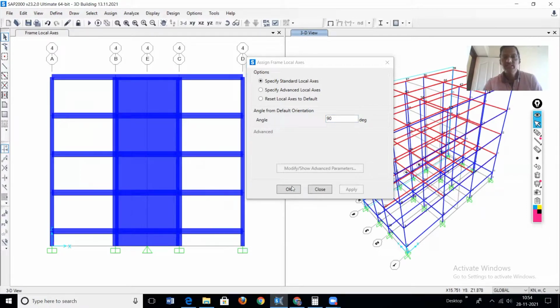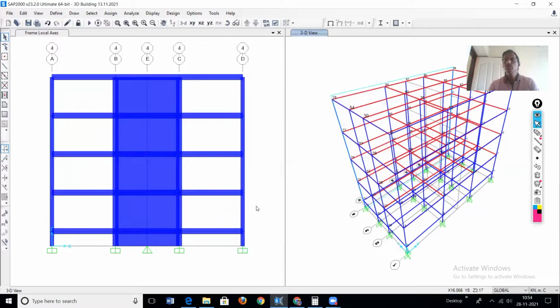Okay, now this is about the definition of the shear wall as a wide column. Okay, and then assign the nonlinearity to this particular wide column, just like a regular RCC column. So in SAP 2000 there are ready-made auto hinges, plastic hinges. So we'll assign the same hinges to this particular shear wall or wide column. Okay, so we'll remove the extrude view of this.